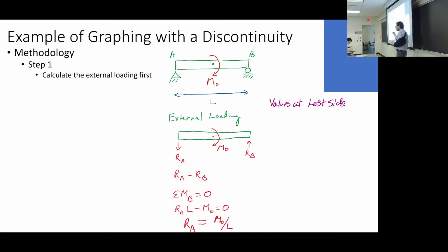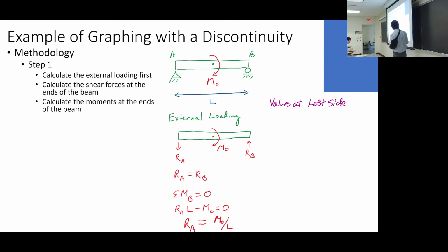But when I draw these across, I usually first draw the values of the left and the right side on the shear force and bending moment diagrams, and it helps me visualize. Often there's 0, 0, and I have to get back to them somehow, or I have some forces and I have to make sure I get back to them.